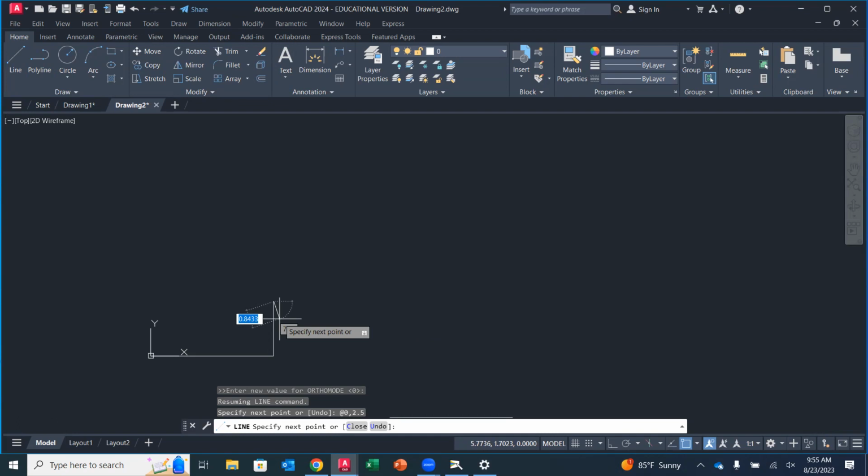Okay. Now I'm going to go over to the right and I'm going to use that same relative. So if I'm on this point right here, I need to go to the right 2.5. So what would my coordinates be? What do I have to key in if I'm going to do it relative to the point I'm at? Go ahead. At 2.5, comma 0. Yeah, absolutely. So now I'm going to go, no, it's relative, not absolute. At 2.5, comma 0, enter. All right, there I am.